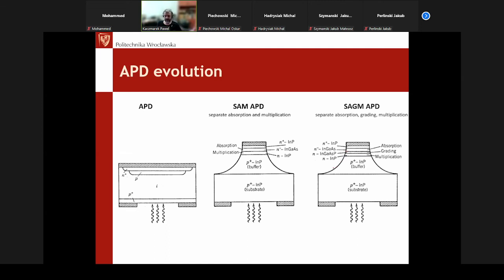to more smoothly transfer from a high band gap energy layer into a low band gap energy layer without slowing the carriers down and so on. Yeah, it is much more complicated to explain to you because a lot of quantum effects play a role here in this grading and in how it works. So I think it is enough for you to know the grading layer is just to increase the frequency, I mean the bandwidth, of such a photodetector. Yeah, so we have some solution for how to have extremely sensitive photodetectors.